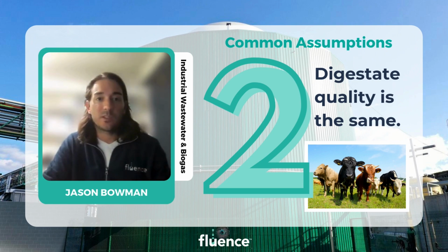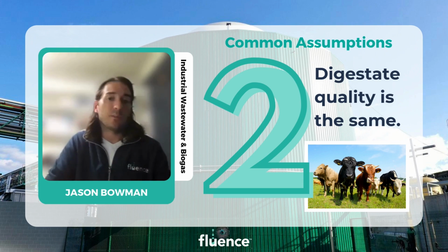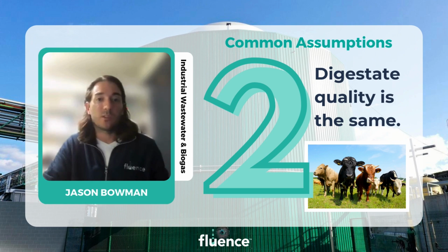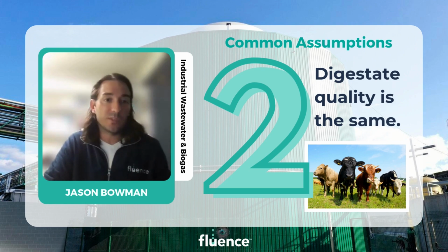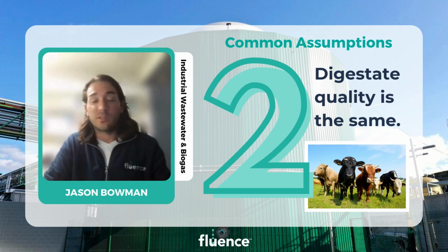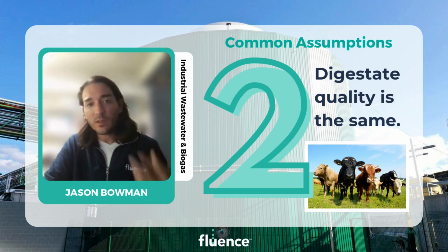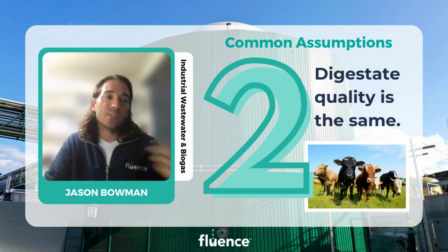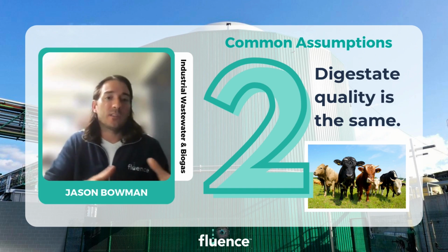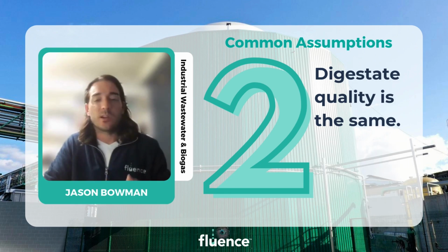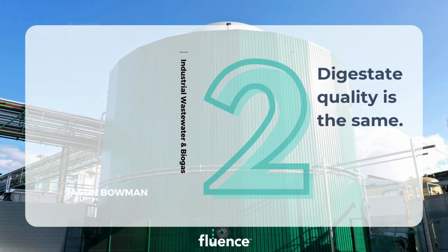The dairy industry is an industry that's used anaerobic digestion for decades. Some of these facilities process waste differently. Sometimes they separate high strength, sometimes they separate the low strength. So some facilities are remote, the logistics are different. Some facilities are a major contributor to the local municipal system while others aren't. So this impacts how they view digestate treatment and what can go down the drain. The point is that when systems take in various and varying conditions, the digestate is going to change. So it's not always safe to assume that digestate is going to be the same from project to project.